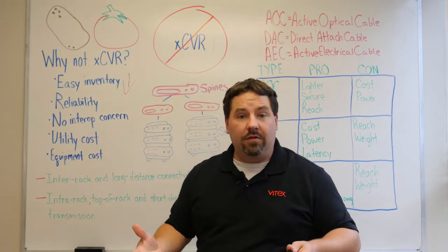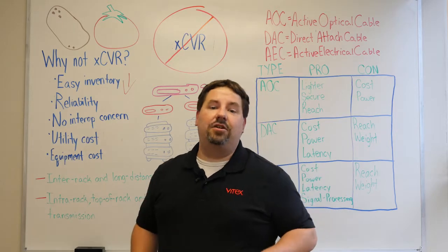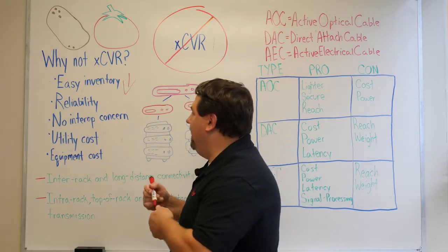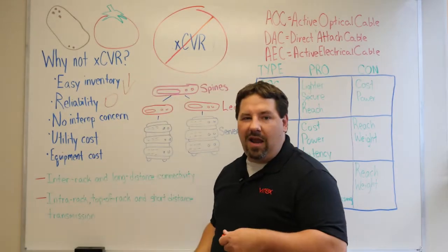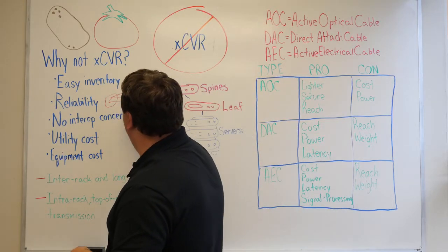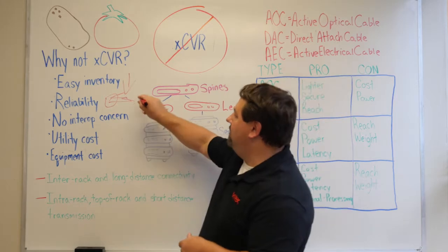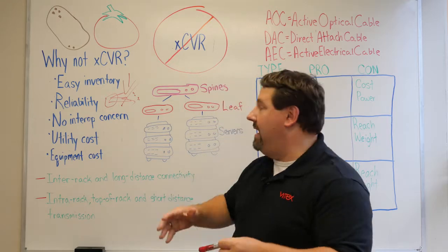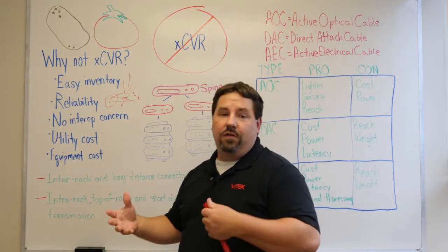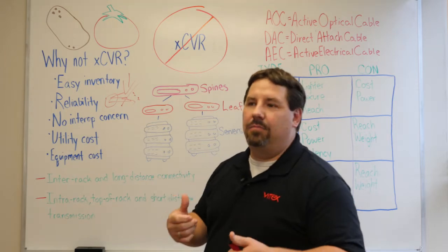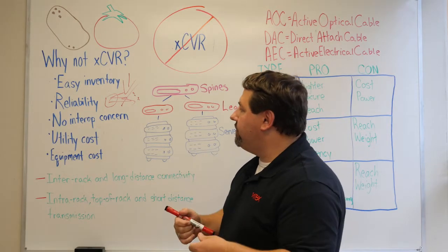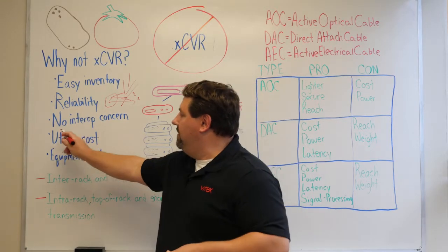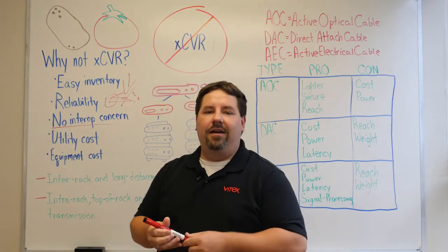So let's look at reliability. I'm not really talking about signal reliability. I'm talking more about connection reliability. If you've worked with fiber cables, we have to unplug them and plug them back in. Let's just take an LC or MPO. Every time we do an insertion or a removal, we have things like dust and scratches that can come into play. But if we have cables that are attached at the factory, this is no longer a concern for us. And so you can see where one of these cabled solutions has much more reliable operation, because we don't have to do insertion and removal of cable.